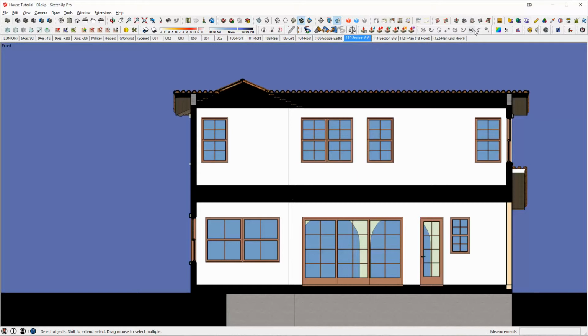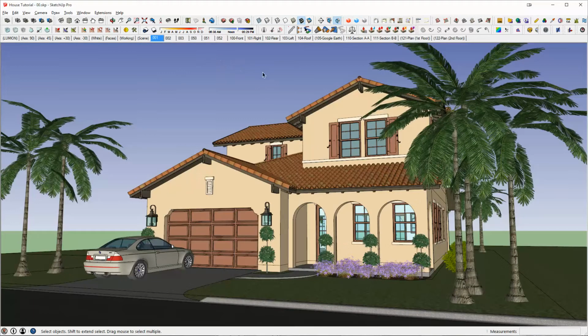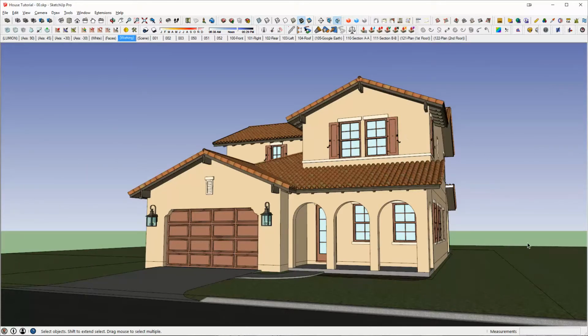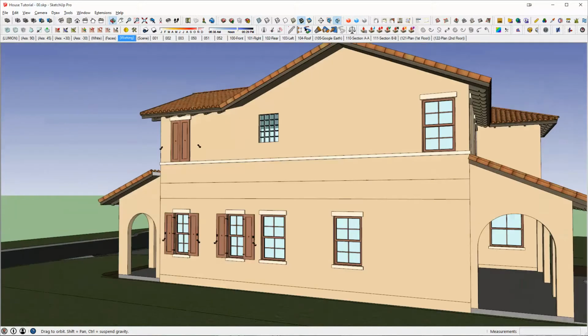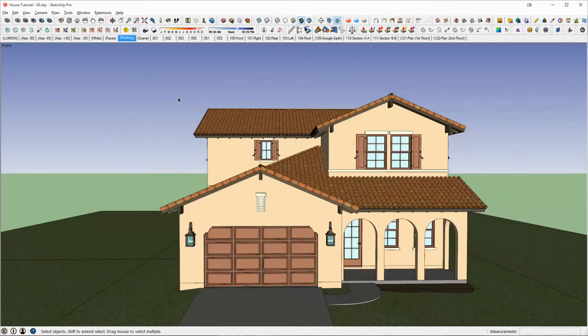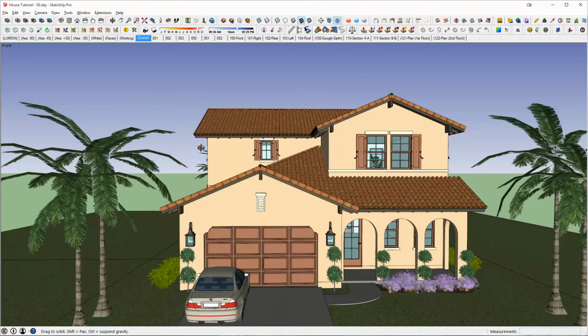And so these are kind of fun tabs that are built in and show you there's quite a bit of things that can be done. Some of the other ones that are useful, again, are my working tab and my scene tab. The working tab is just quick layer controls, which get rid of all the non-essential items, like the trees and whatnot that really slow down modeling, so I can just deal with just the building itself. And my scene tab puts everything back on.